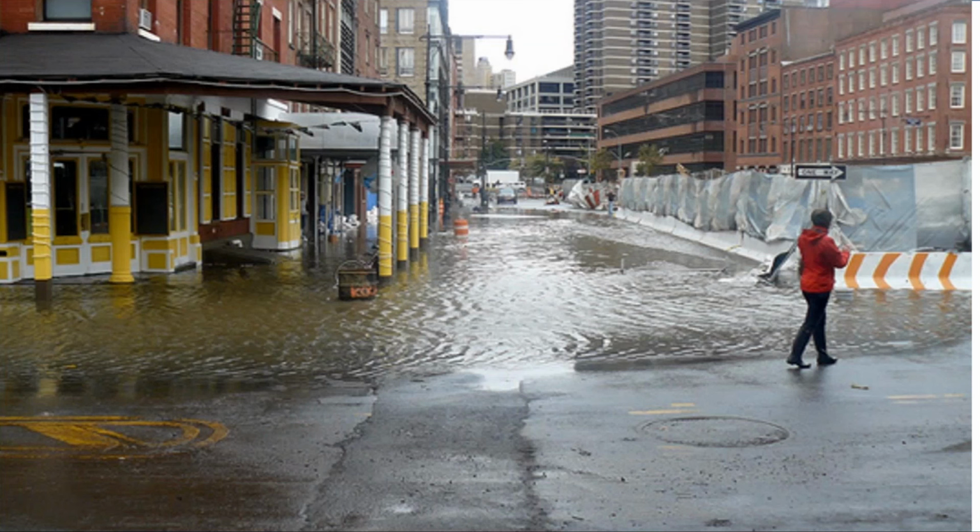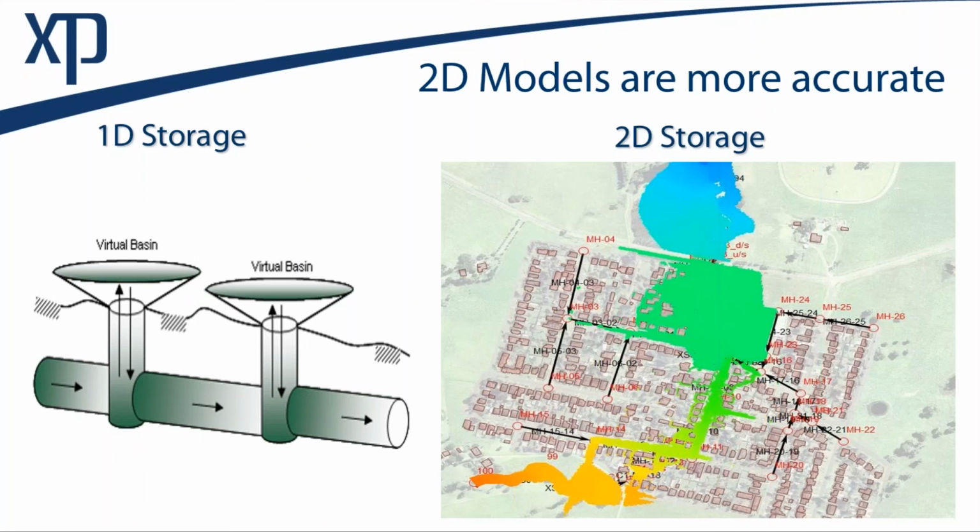This is what happens in an urban area when water comes out of the 1D network. It impacts, it pools up based on the surface elevation. It interacts with the 2D urban environment around it, sloshing up against the doors, maybe seeping in and flooding the basement, or running down the street and into another manhole at a lower elevation if capacity dictates, and so forth. So it's very dynamic, the actual urban environment, and really not much like the 1D representations that we used to have that would just store the water in place.